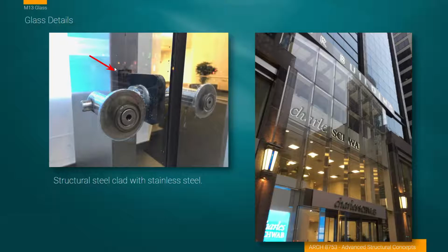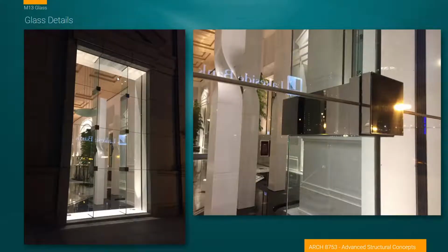Their cost would be many factors over typical steel. And so at that point, when value engineering happens, there need to be these compromises in order to make the project affordable. In this case, we're using a steel column and then cladding it in aluminum to give it the aesthetics that we want.